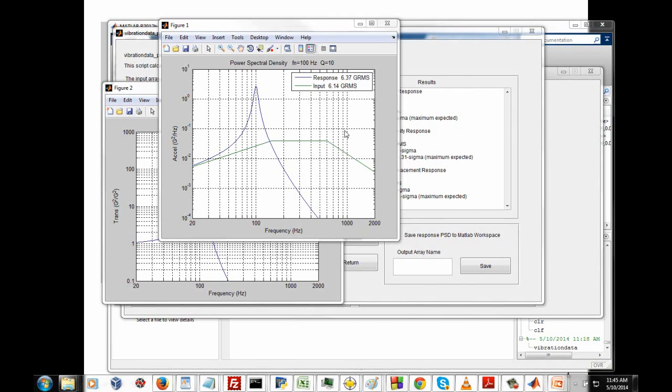If we're working with maybe a one-of-a-kind avionics box, or there's just 2 or 3 of them for 2 or 3 different flights of the same vehicle, the program managers might not want to spend the money to give us a spare unit to do the type of mechanical engineering tests we would like to do. So a lot of times we just get stuck, and we have to make estimates as to what the lower and upper frequency bounds of that circuit board inside that box would be.